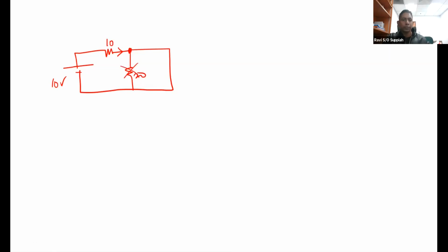with the inductor, correct? Or with the capacitor, because when the capacitor becomes fully charged, it becomes an open circuit, so no current can flow. In this case, the same thing, but what you have is a short circuit pathway. It's easier for the current to flow through a short circuit path than to flow through a resistor. So all the current will actually flow through this short circuit path and skip the resistor.